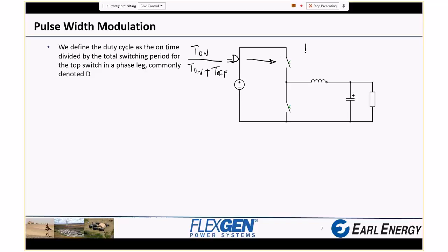So when we had 10 volts in and we wanted 5 volts out, with this definition you get V out equals V in times D. Since we wanted 5 volts on the output and 10 volts on the input, you end up with 5 over 10 equals D equals 0.5 equals 50% duty. That is what we ended up with there.